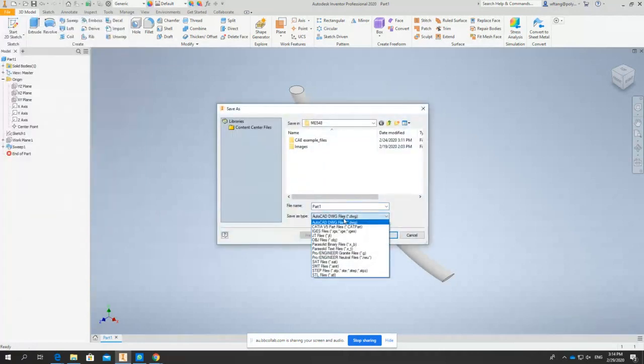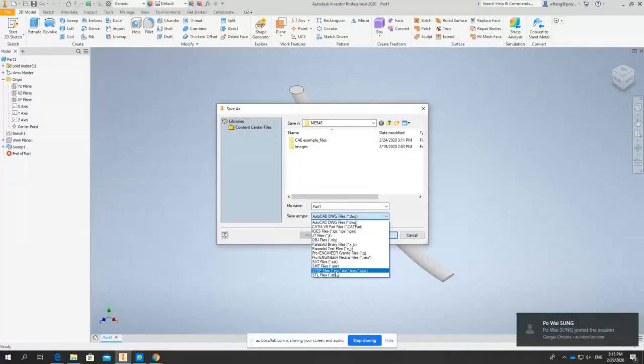Don't use the Parasolid one, use the STEP, because when you use Ansys Student we can't import Parasolid. Your version you can't. With a commercial license we can import the Parasolid, STEP file or IGS files. It is two different software. In our laboratory we can use Parasolid to make it.